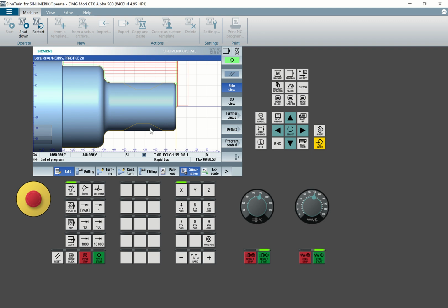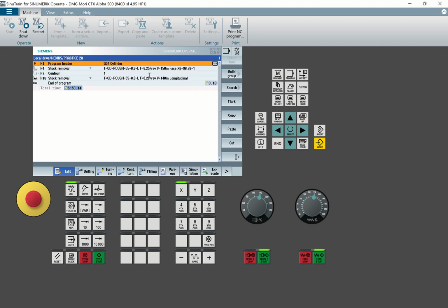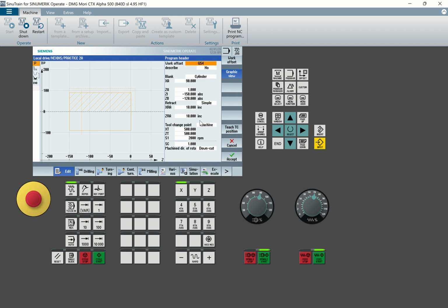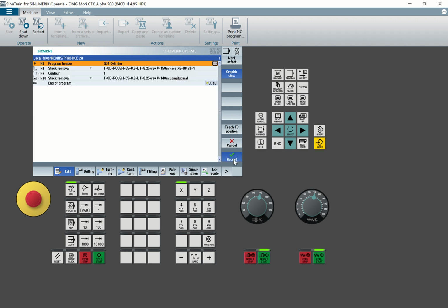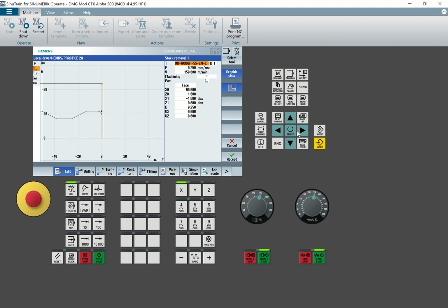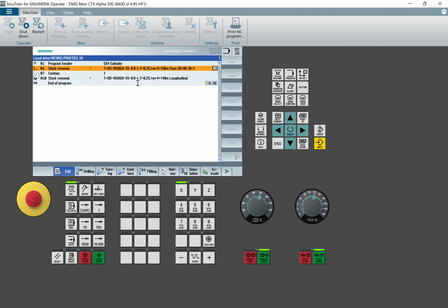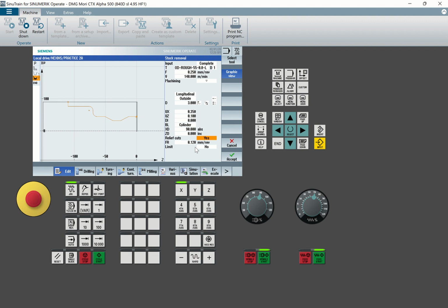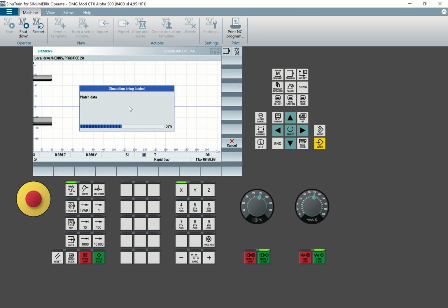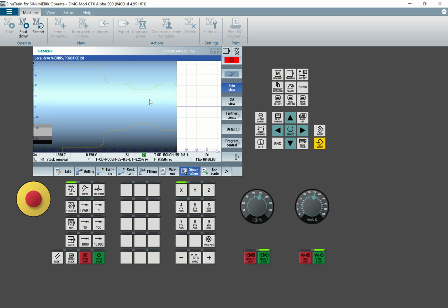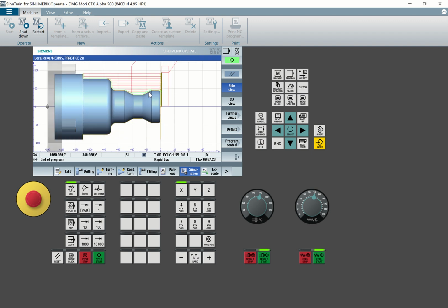Come here and edit. Go to the first part for the header. Check here that all the parameters are okay. Once you're okay, come to the stock removal for roughing. Ensure that you check that all parameters are okay. Now go to this stock removal for roughing. Ensure that you say there's undercut, so that it takes the material going inside the curve, so that the tool can now cut. Then click OK. If I do a simulation, you'll see the tool now enter the material to cut, so that it doesn't leave any amount. So as you can see now, doing turning, it has cut this undercut.